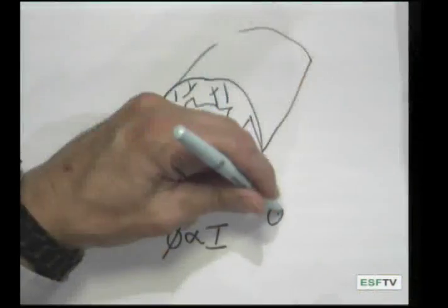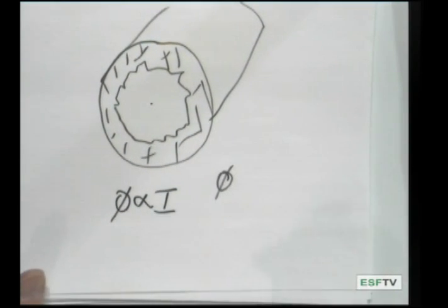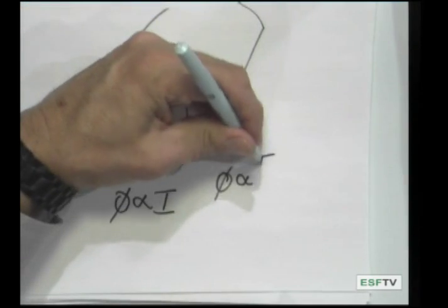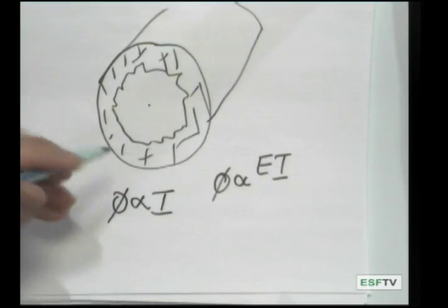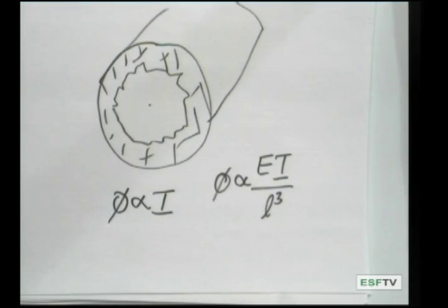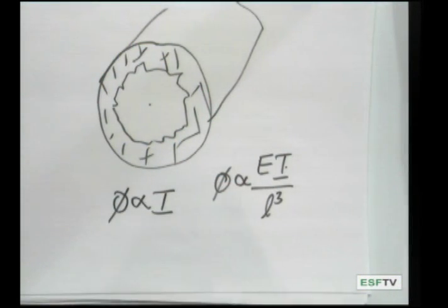Again, there's nothing complicated about this. We can look at our flexural stiffness and all the things that feed into it. In the case of flexural stiffness, we are looking at a proportionality that considers the Young's modulus of elasticity, the second moment of area, over the cube of the length. And so what really determines the stiffness of an object is this product of the Young's modulus, the material property, and the second moment of area, which determines its distribution.